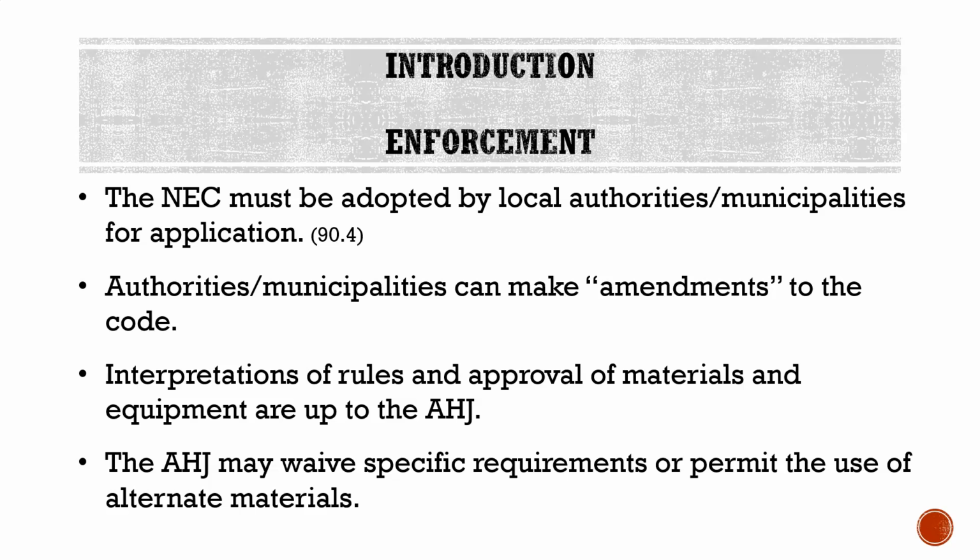That's an important note that I usually mention before now: the code, the NEC, is a minimum installation requirement. You cannot go below the code, but you can always install above the code. So for that earlier example, even though the code says you do not have to use a grounding electrode conductor larger than a number 6 for attachment to ground rods when they are used as a grounding electrode, there is no rule against using a larger conductor. You could use a number 1 conductor if you wanted to, but you have to use, at a minimum, a certain size conductor, which could be a number 8, it could be a number 6, and so forth. So just to reiterate, the code, the NEC, is a minimum rule. You can always go above the code.